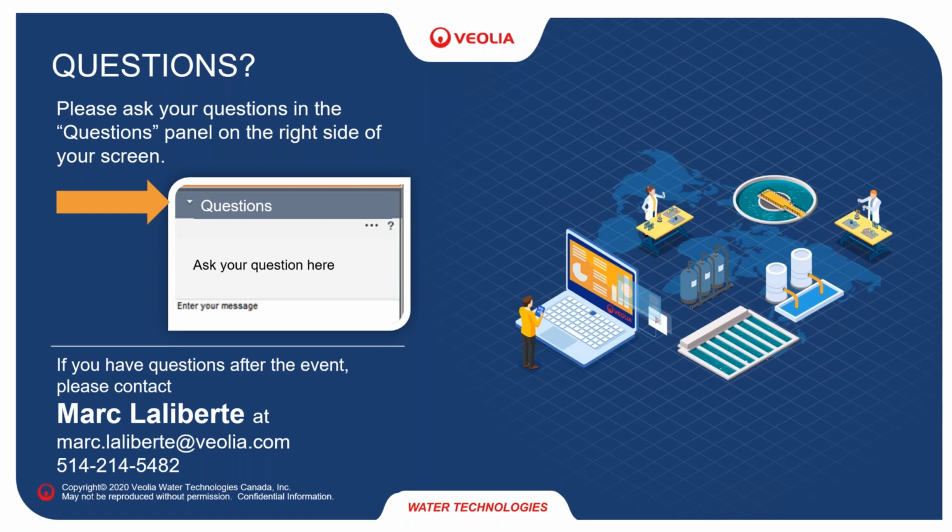However, we can fairly easily treat the sludge to increase its solid content. As I said earlier in one of the slides, actually in the slide for case study 3, it's very project dependent. Sometimes the client has a way to deal with the sludge. Maybe there's already a pond or something. If not, what we do for remediation most often is use geotubes, because for a temporary application, it's labor intensive and does require space, but it is very efficient.